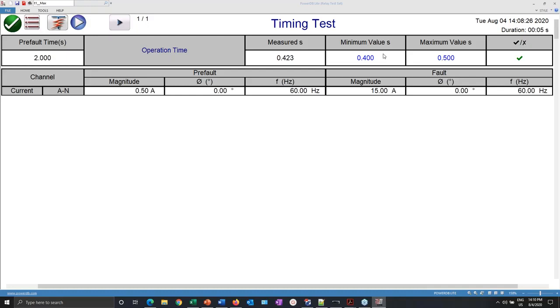Of course, the tools that we have allow you to do this kind of testing more easily, but what our tools do essentially is use this same concept. They inject magnitudes into the relay and sense the outputs of the relay, and then evaluate the tripping or not tripping of the relay, depending on the conditions and the settings that the relay had.